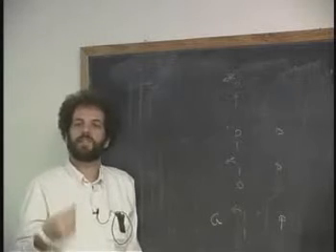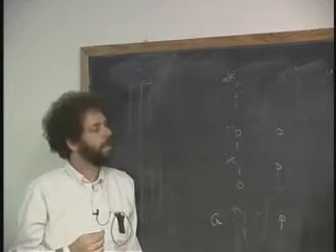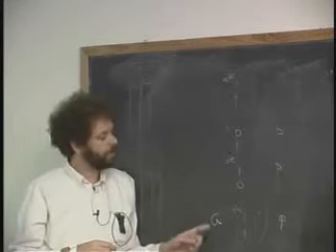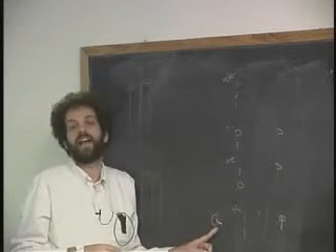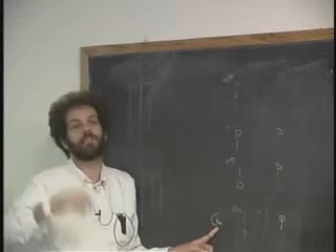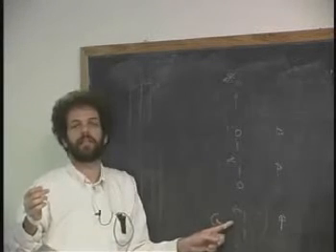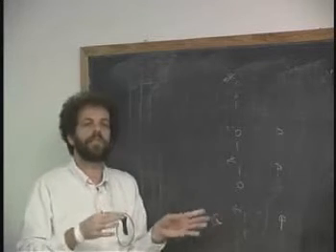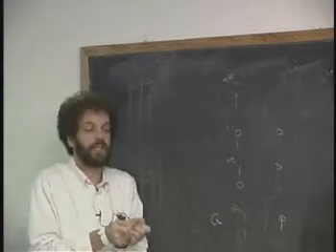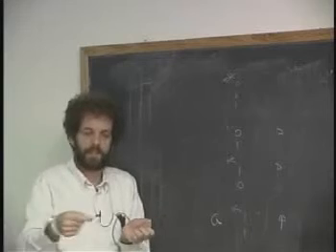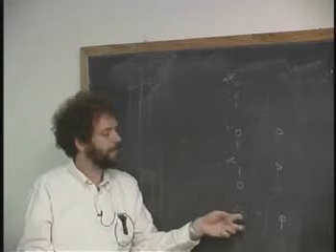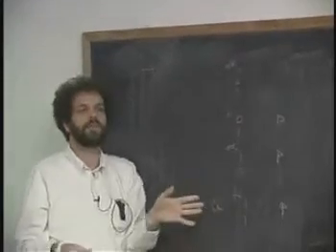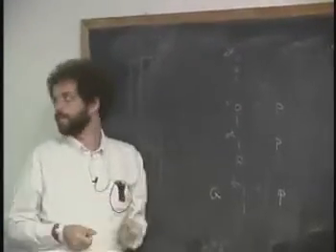Now this decision, do I generate or do I propagate, can be made beforehand, before the carry comes in. First of all, the generate, you can even take action on before the carry comes in, because it doesn't matter what the carry-in is, in this case, you just generate the carry. And in the propagate case, you can get all the work done and all set up, so you're just waiting for this last bit to come in, which is a slow bit that's going down the chain. If I have two 1s, or if I have a 1 and a 0, I get all set up waiting for the propagate to happen.